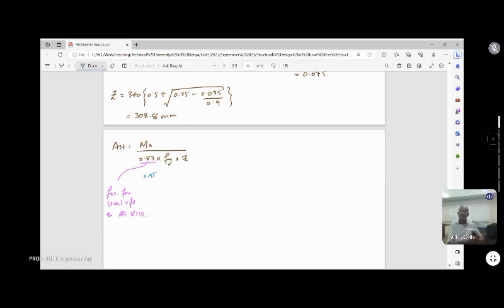But because we have improved a lot in terms of our quality control in manufacturing of reinforcement steel, now we can use up to 95%. It is safe to use 95% of the characteristic strength of the steel that we produce. So that is the Britons. I'm thinking even in the Eurocode, this factor of safety is 0.95.